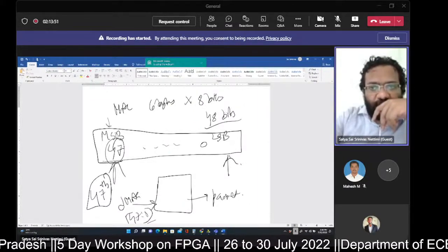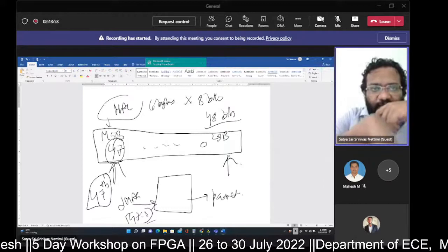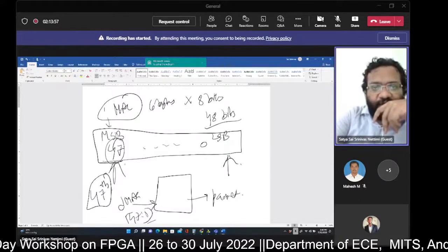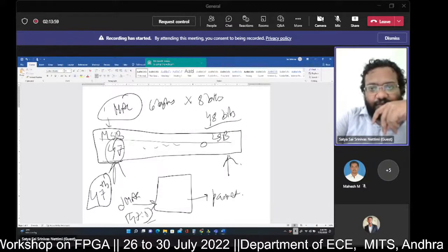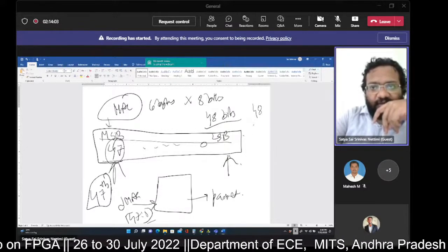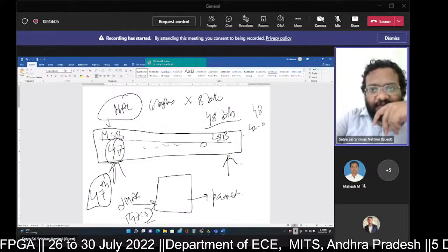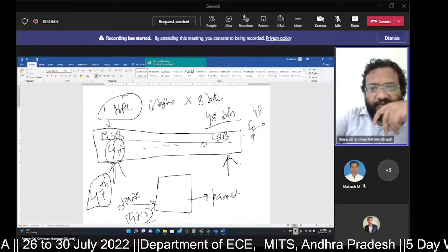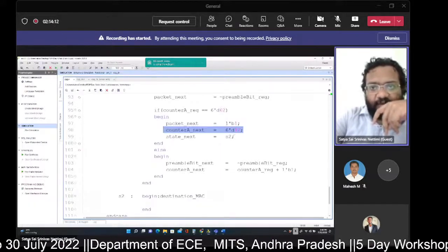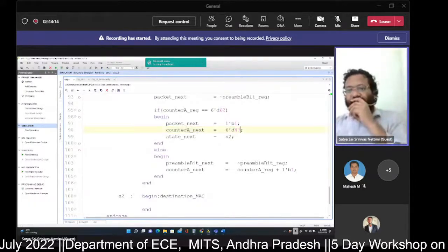First of all, I want to reuse that counter for destination MAC address retrieval. And while retrieving, I have to retrieve the address from the MSB side to the LSB side. Since it is a 48-bit length, it ranges from 47 to 0, so I need to scan the 47th bit first. For that purpose, I am resetting the counter to an intermediate value, that is 47.